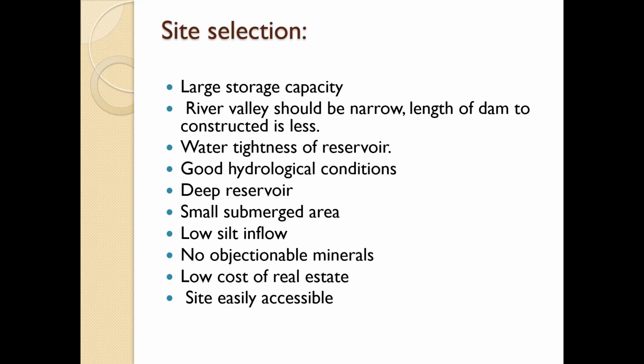Then no objectionable mineral should be there, so that the water does not get polluted because of that mineral, and no adverse effect will be there on the health of the people using water from that area. Then the real estate cost should be low, because if the area is developed and goes under the dam site, that is not of use.